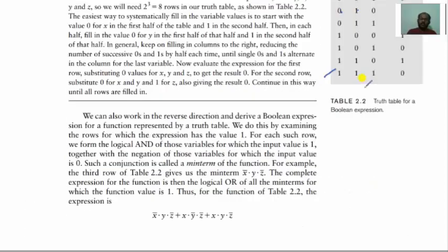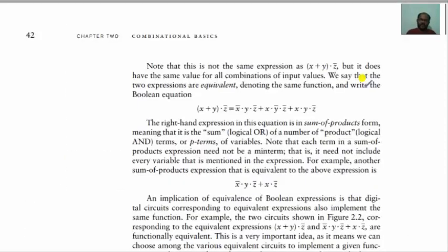Now, how are you going to write Verilog code for the given expression? The given expression is (x plus y) into z bar. Let me assign this to a. That means a equals (x plus y) into z bar.